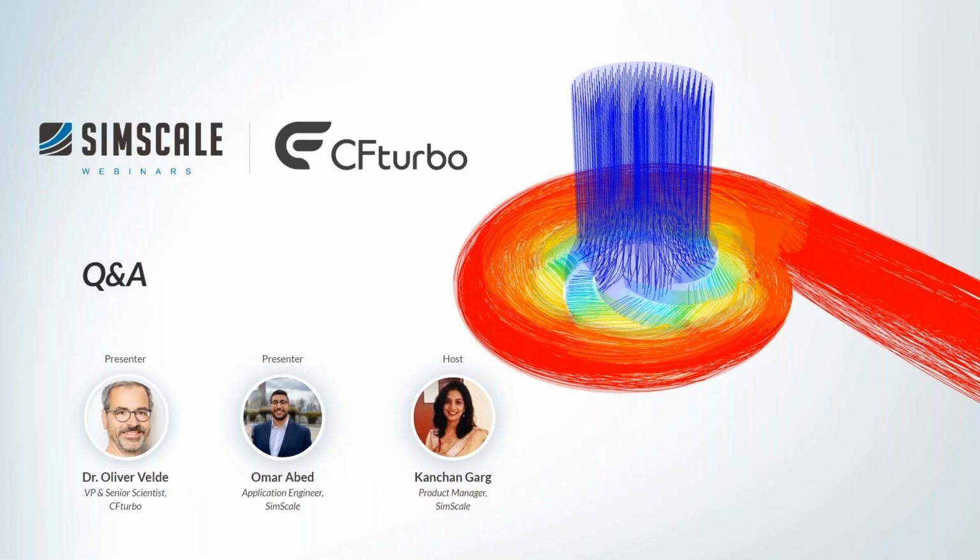So basically, all the parameters that you could change in the GUI can also be changed in a batch mode, for instance. And as I said before, you will find those parameters that you would expect as a hydraulic designer, like blade or wrap angles and number of blades and so on.